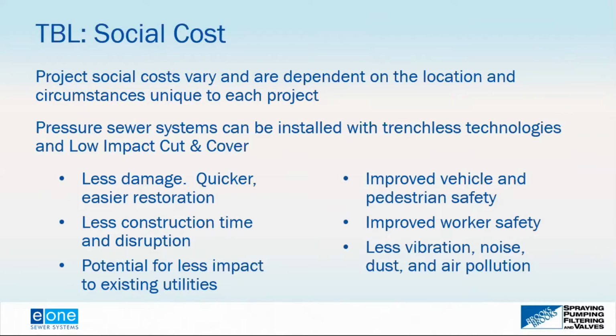There's less construction time and less disruption. So the contractor can install more pipe per day with a low pressure sewer system than they typically can with a gravity sewer system. So you're going to have your crews and your construction equipment in the community for a shorter period of time. Potential for less impact to existing utilities.